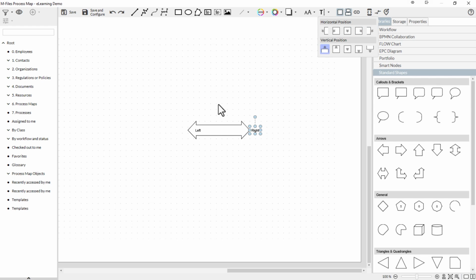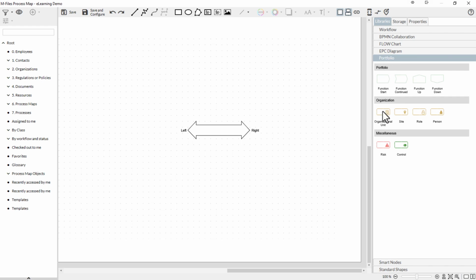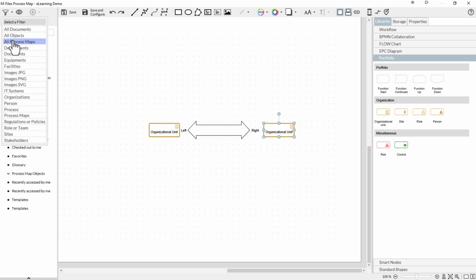For example, imagine a piece of equipment where you want to label the various aspects that are already existent as metadata, like its class, machine status, its owner, the manufacturer, related processes, etc. If you want to enter static text, you can simply double-click a label and enter the text. Shapes that don't have a label yet, for example a line, a circle or rectangle, will automatically add the first label when double-clicked. But the context menu Add Label works just as well.